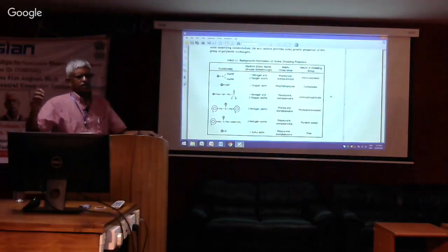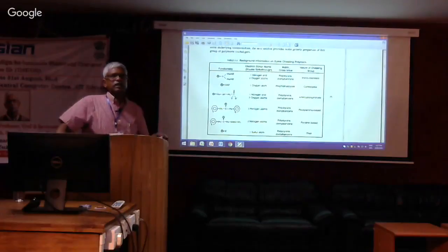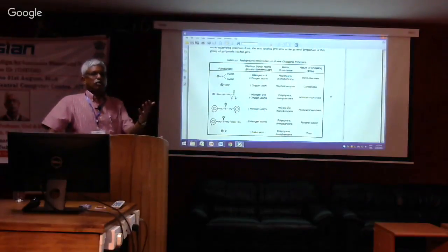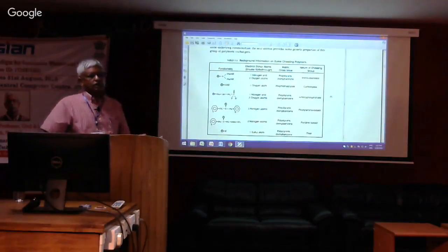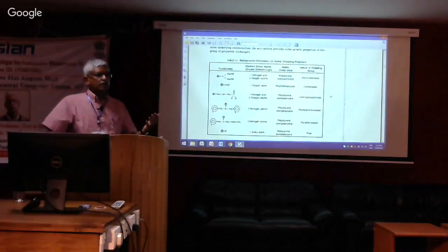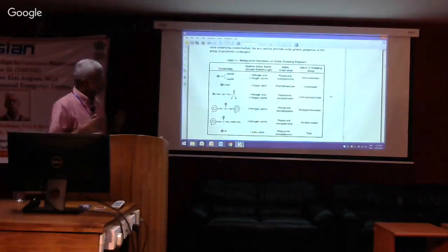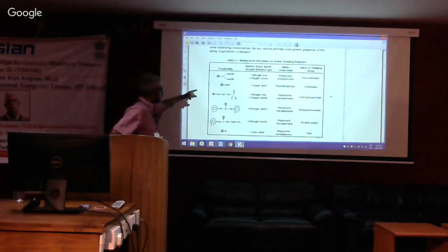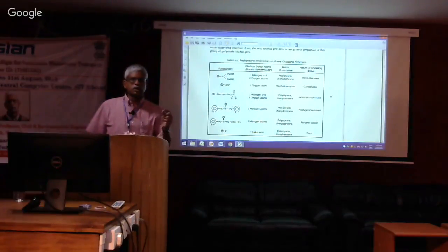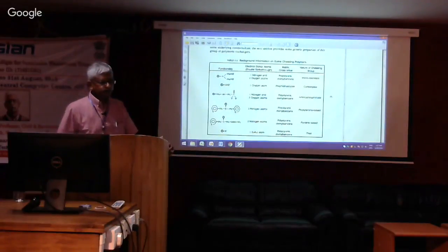Their concentrations may vary. So then you have to decide what is your most important heavy metal that you're trying to remove, and can you live with, let's say, a few milligrams per liter of heavy metal Y still in the solution? In such cases, you have to look at the binding constants and then decide which particular heavy metal I should choose to remove.